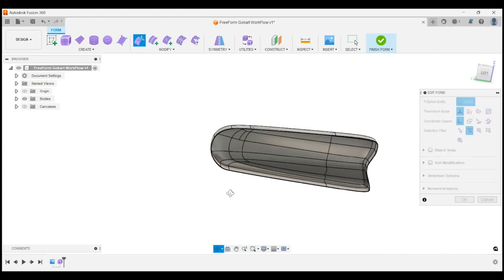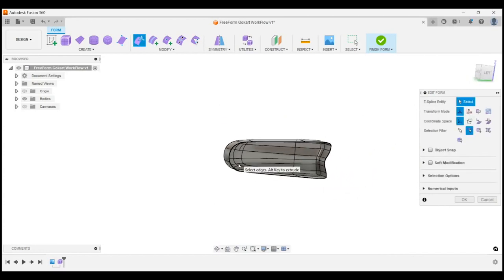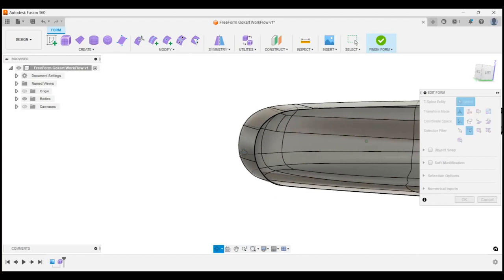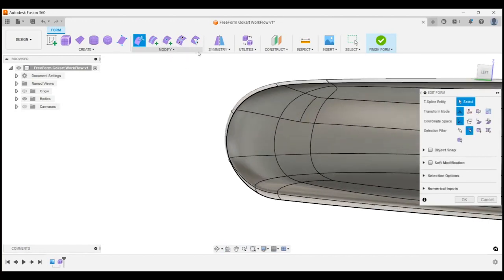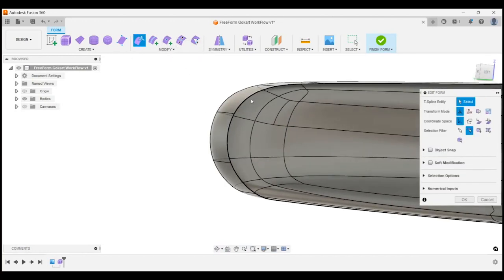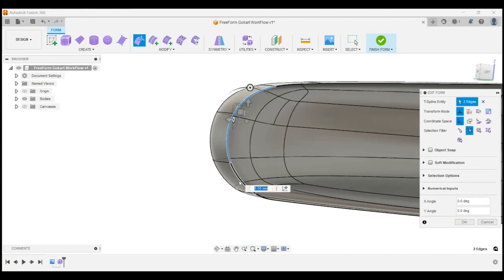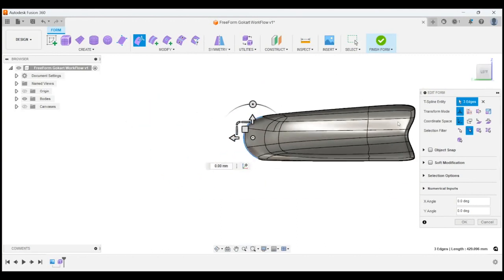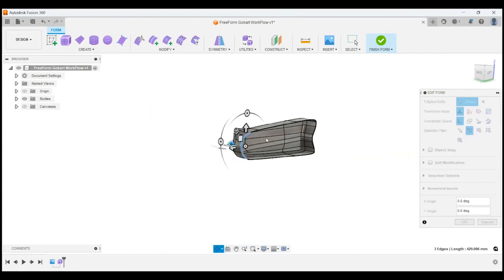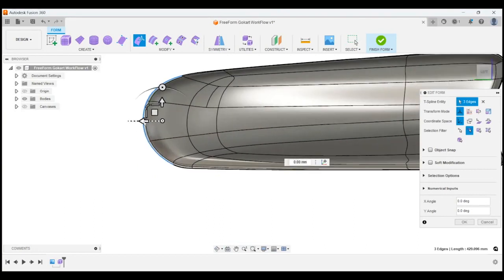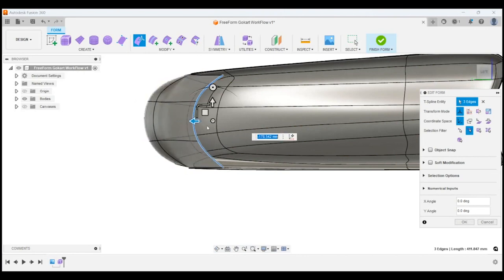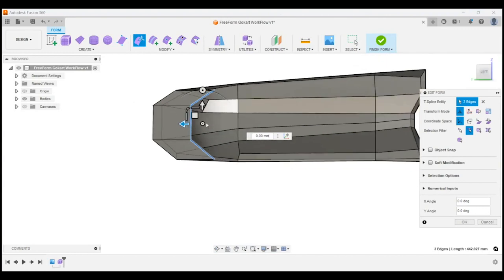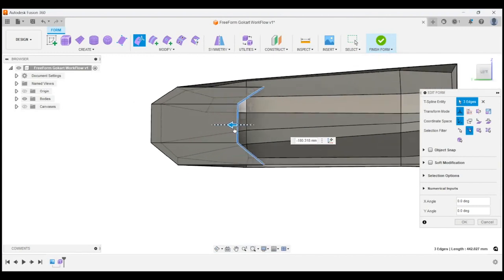So when we're finishing off a body, counting faces is extremely important. So what I'm going to do here, I'm just going to demonstrate how we'd close this shape off. And that's by selecting the point with fewer faces. We could also close it off from the back forward, but then we'll end up creating a lot of T-points here at the front. So we'll go from the front backwards where the fewer faces are. So first of all, hitting Alt, and now I should be in box display for this actually, sorry. Hitting Alt, and we'll bring this back to this point here,